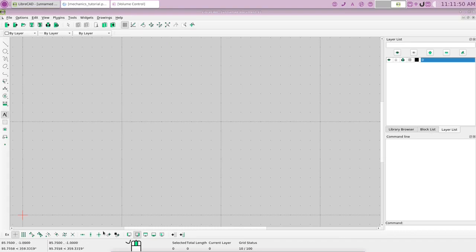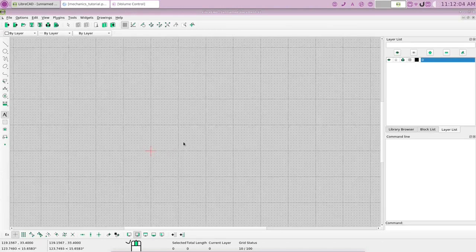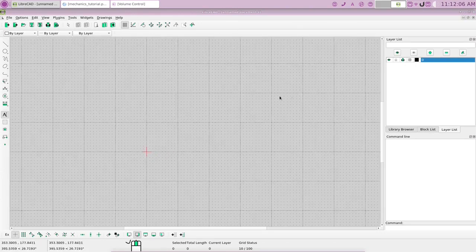drawing, you'll want to get used to these tools down here. These are your snaps, and you see it opened with the default on free snap, but this is snap on grid, and the grid is these little dots you've got right here. If you zoom way in, you can see these are the little dots of your grid. So if we put snap on grid on, then when we're trying to draw a line, it will snap on each of these little dots here. Okay?